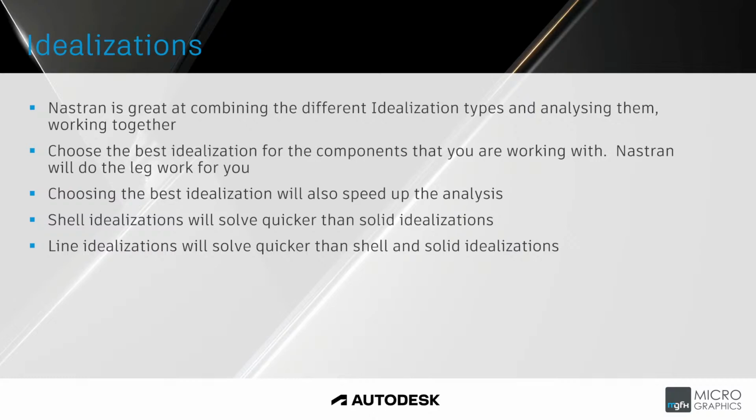You just need to choose the best option to make the FEA run as quickly as possible, because that's really our goal here. You want to get the most accurate result, but in as quick a way as possible. Maybe you don't have great hardware, so you've got to choose the correct idealization for that. Solid idealization is probably the slowest idealization to run an analysis. Then shell idealizations will solve quicker than solid, and linear idealizations will solve quicker than both shell and solid idealizations.